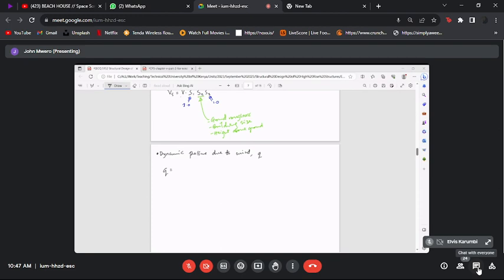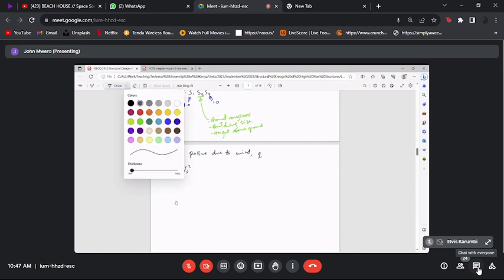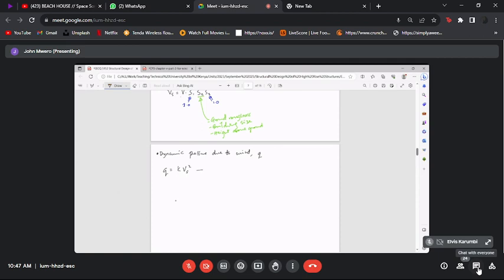Q, from this standard, is given as K Vs squared, basically just the square of the design wind speed, which is site specific, multiplied by a factor. For this standard, K is given to be 0.613.